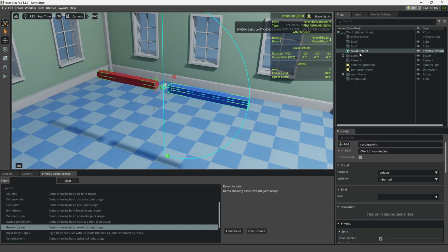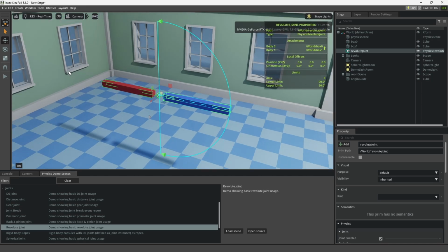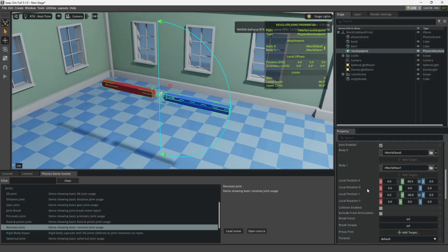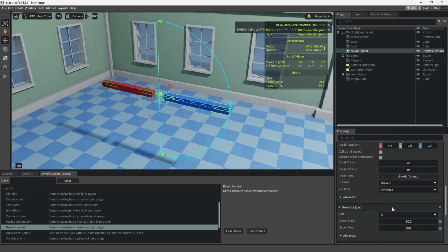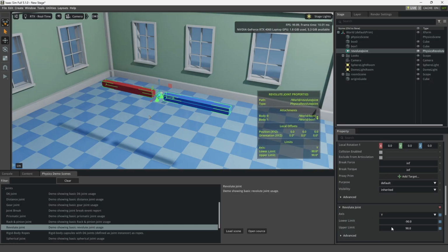But if you click this Revolute joint now, because we had that joint view set, we can see the parameters again, which are really valuable here. This is really an important piece to understanding the joint, because now you can come down to the Revolute Joint's axis and change it to Y, and you can also change it to Z, and you can see what's happening.